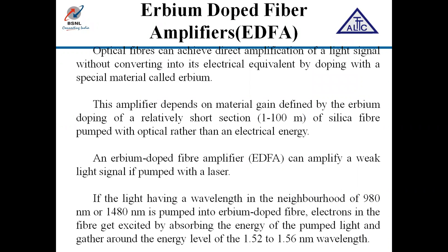Here, the erbium doped amplifier is explained. This amplifier depends on material gain defined by the erbium doping of a relatively short section of silica fiber, with optical rather than electrical energy. There is optical pumping used in EDFA. An erbium doped fiber amplifier can amplify a weak light signal if pumped with a laser.